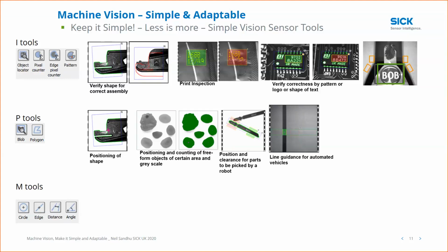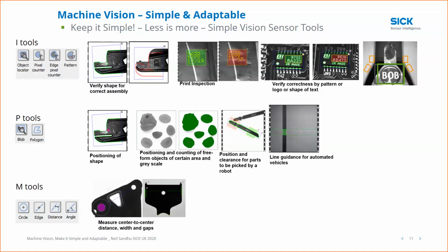And with measurement tools, we can see that they can help a vision sensor perform quality inspection tasks when manufacturing, again, components, making sure in this case holes are perhaps produced and pressed in the right areas, they're the right size, the right distance away from certain edges. So that's all part of measurement tools. Here you're measuring the widths and lengths of components, as well as circular tools and angular tools to make sure that things are manufactured at the right degree.